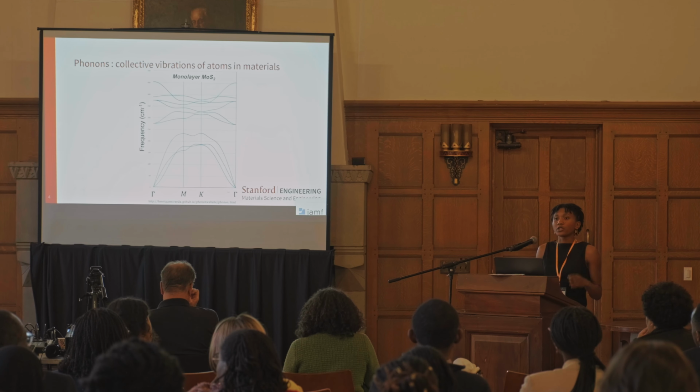So now we have these nice monolayers, but we want to make some bubble wrap. To do this, we developed a technique where we can engineer nanoscale local periodic deformations into the material and control how many there are and their shape and size. We do this by transferring the monolayer using a polymer, a sticky substance, to just pick it up. We transfer it onto a rigid periodic mold. Because these layers are so thin, they're able to conform to the mold.